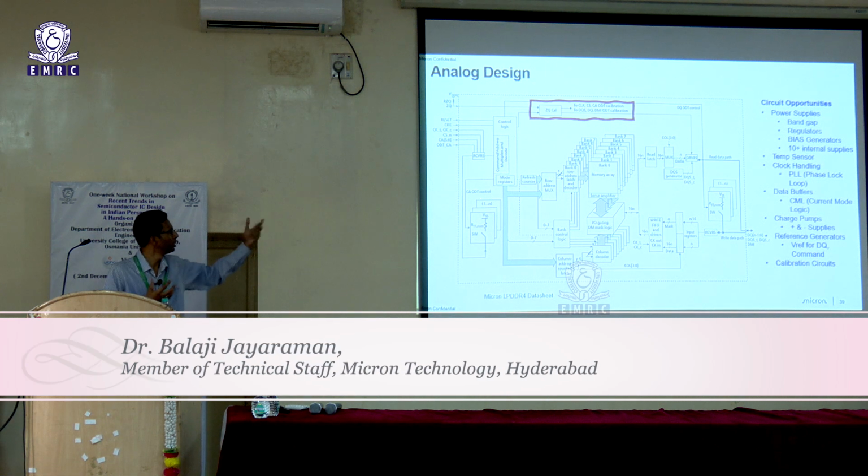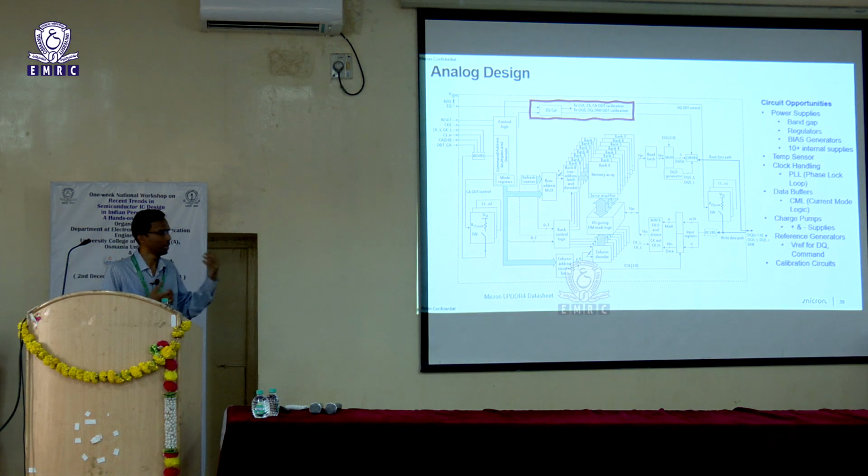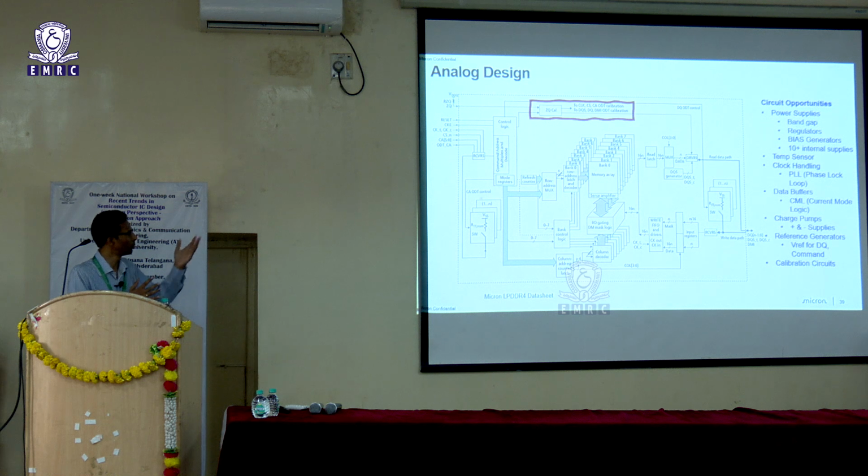So you need to have charge pumps, and the charge pumps by construct would need a band gap reference to be pumped in, and then you will also need voltage regulators. So if you look at the overall construction, we would have multiple internal supplies within a DRAM chip, more than 10 easily. And we also need a temperature sensor.